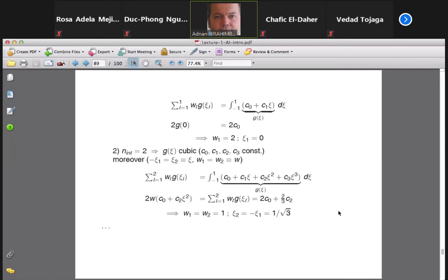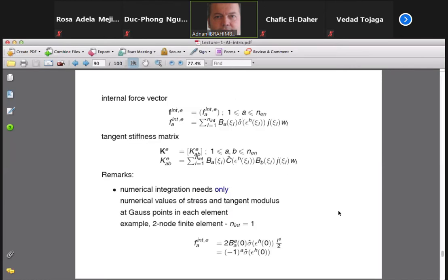So what you can do is go back and complete the homework by using numerical integration, and you can decide how many integration points you need to compute the stiffness matrices, and you can test whether what I told you is correct. For example, if you take a two-node truss-bar element, it should be enough to have a single Gauss point for numerical integration.